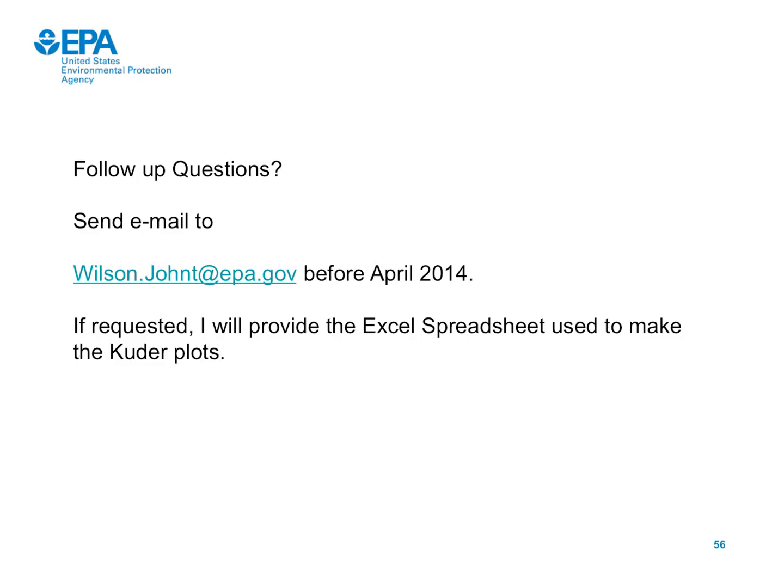Okay, there's another question that says, would analyzing the groundwater samples for ethene, ethane, and chloride also be a valid method for determining if vinyl chloride is degrading? Depends on the numbers that you get. If the numbers give you a clear, unequivocal pattern that you can interpret to a regulator, yes. If they don't, then you need to talk to somebody about CSIA. But I would do what's described first, and then if that doesn't work, then go the next step.